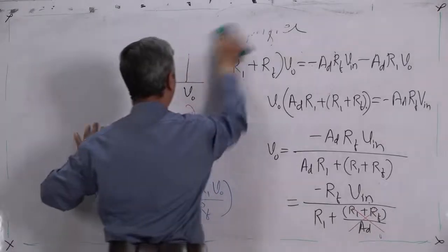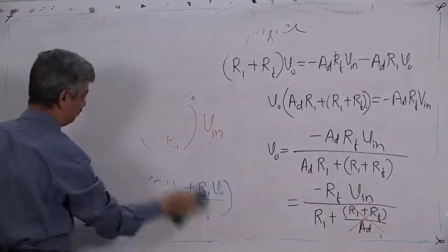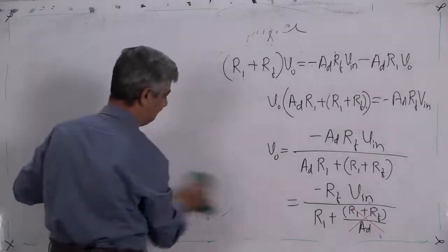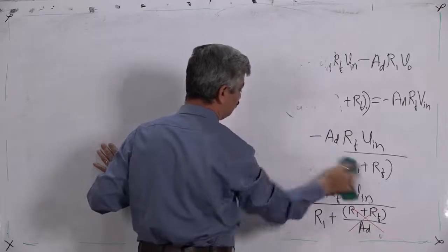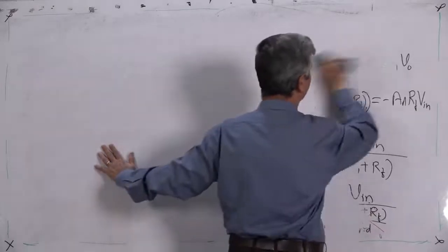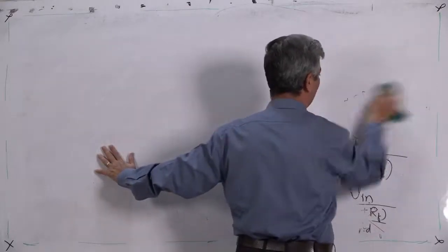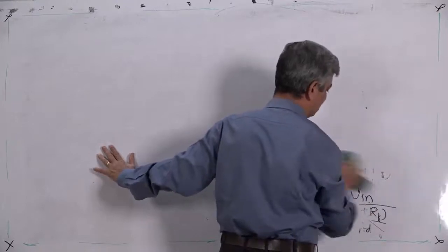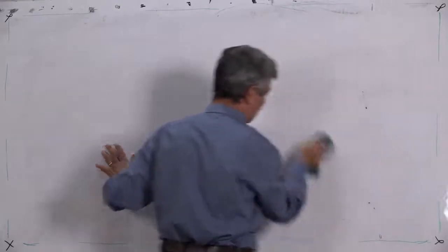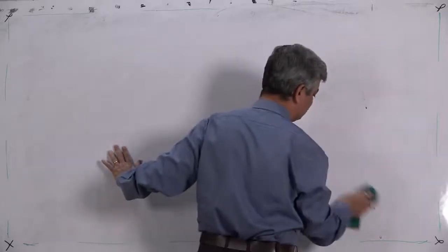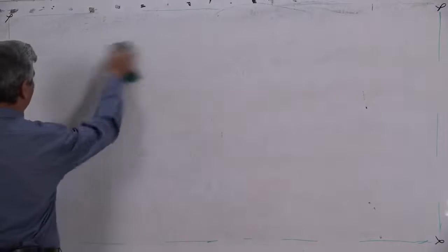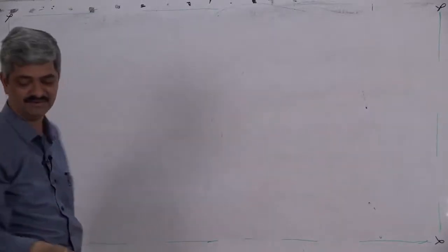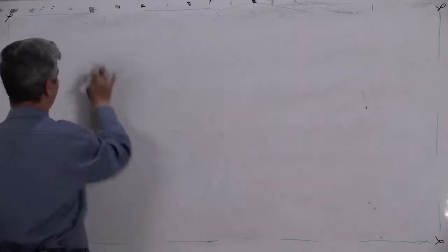The meanings of the circuits I will write first so that you can have some guess, and we will proceed further. So each time, as I had already stated, there is no need to calculate everything once again, this AD, and then dividing by AD, then saying that it is very small, so ignore. Assuming this AD is very large, assuming that the op-amp draws no current, there is a simple formula which I will tell, a thumb rule. How to deal with an operational amplifier?